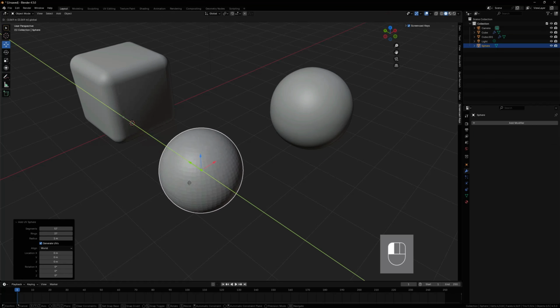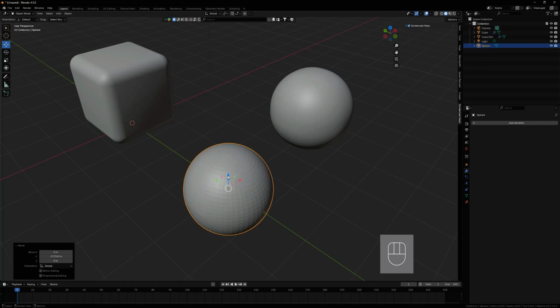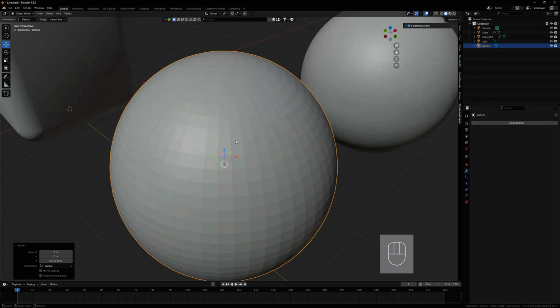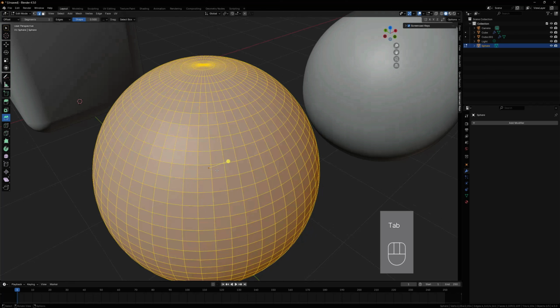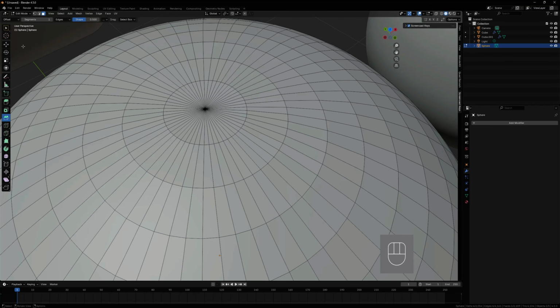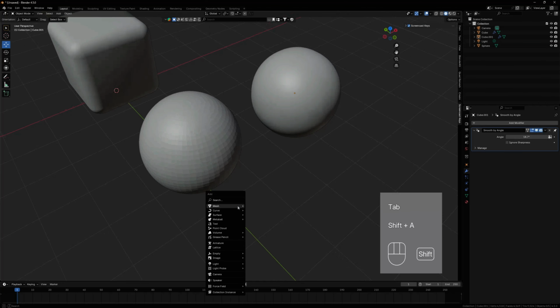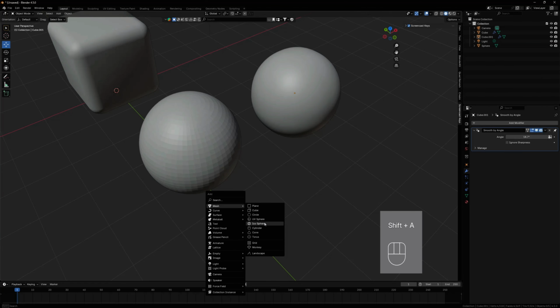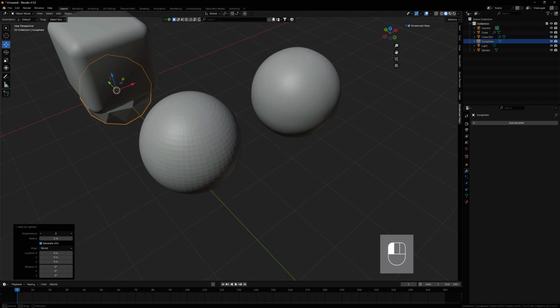Blender's default sphere is not entirely quad-based. All segments end with one vertex, leading to triangular faces on both ends. Mixed triangle and quad topology in 3D models can cause issues because they behave differently during processes like rendering, animation, and texturing.